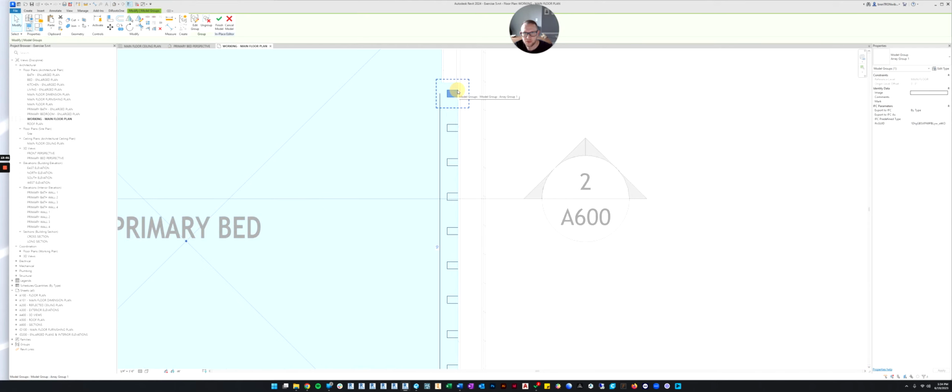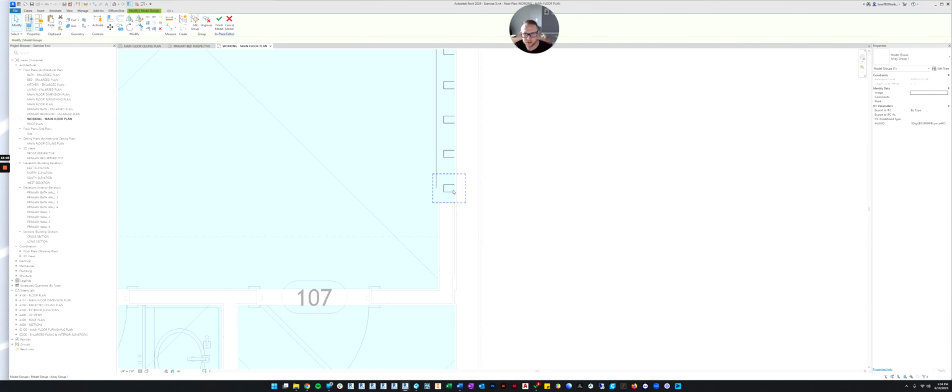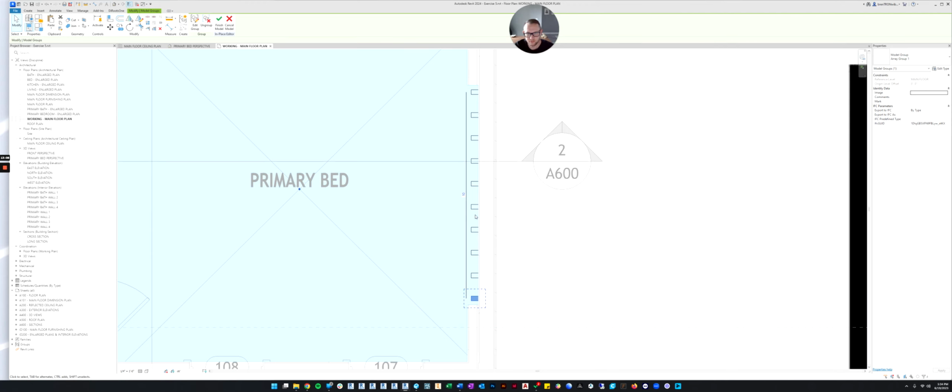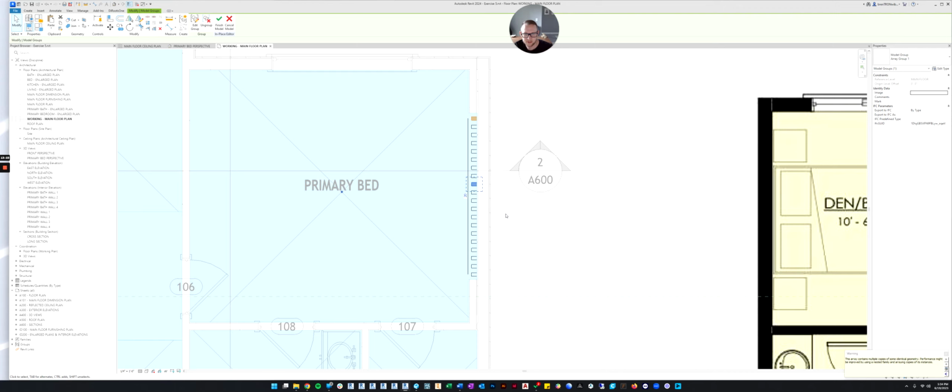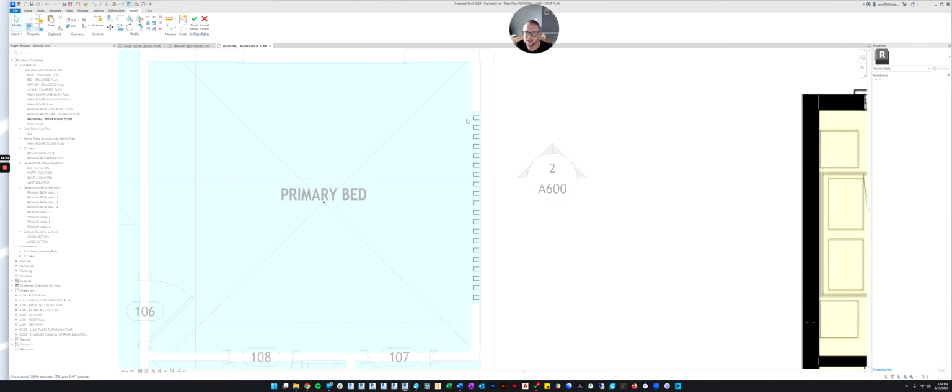That's pretty good, but we want this one to be scooted further down like that. And now it keeps 10 in there. So if I click on any one of the array members, it brings up this little line with the number. You can click on the number and we could do 20, for example. Or maybe we only want 15. 20 was pretty good. Let's do 20. So now there's 20 slats. In fact, we could even do more. Let's do 22.